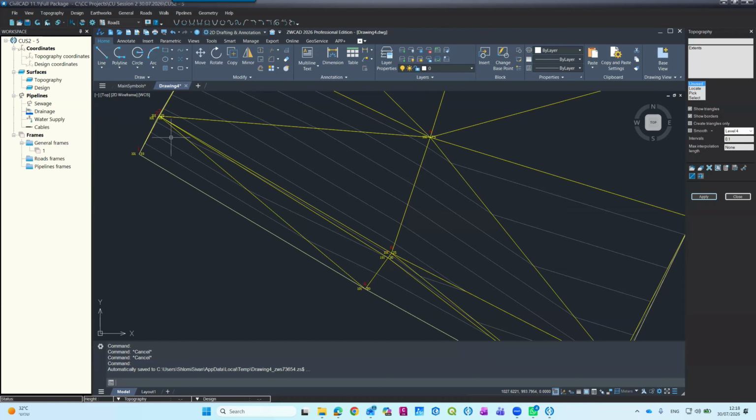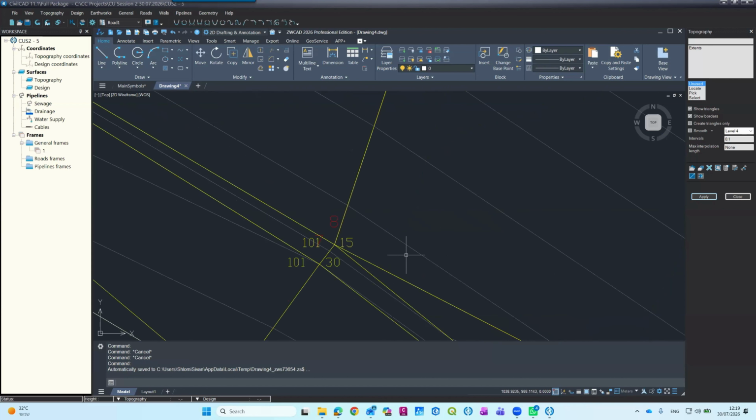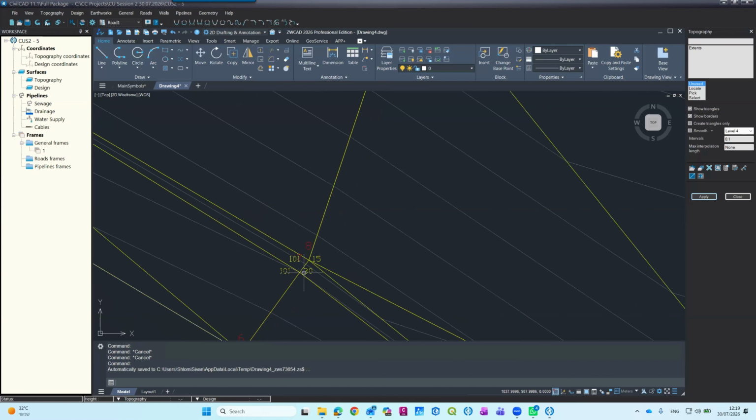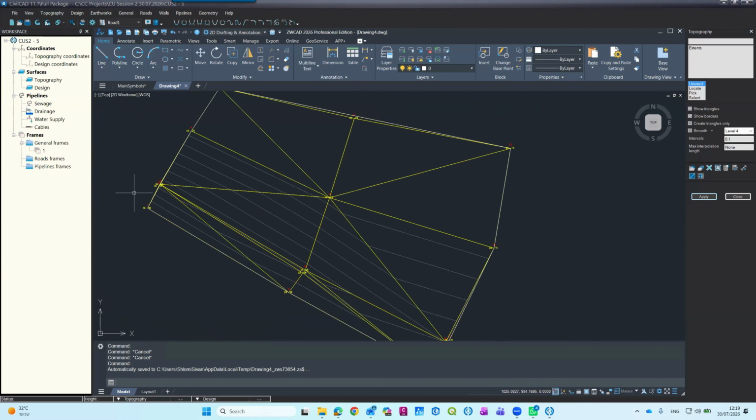Physically in the field, we usually create breaklines along a steep fall. So you might say, but this is not a steep fall, this is 15 cm. It's a steep fall because, compared to the difference here, which is probably a few centimeters, it's steep. So we'll do it along a cliff. In roads, we'll do it at the bottom of the ditch or the top of the ditch. We'll do it along a sidewalk like here. How to do it? Let's do it together.